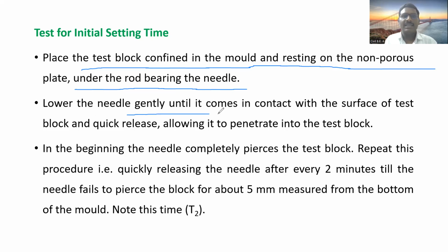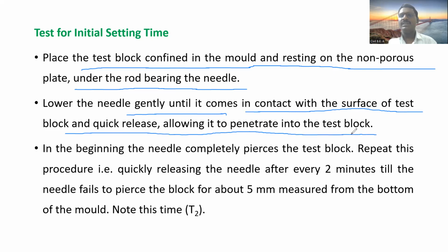Then lower the needle gently until it comes in contact with the surface of the test block, and quickly release it, allowing it to penetrate into the test block. So we have to keep this needle at surface level, and then we have to release the needle, so that the needle will penetrate into the block. In the beginning, the needle completely presses into the block.